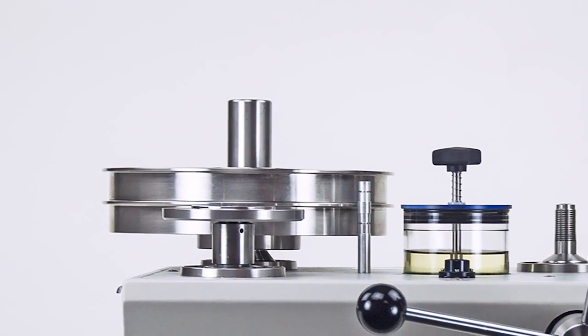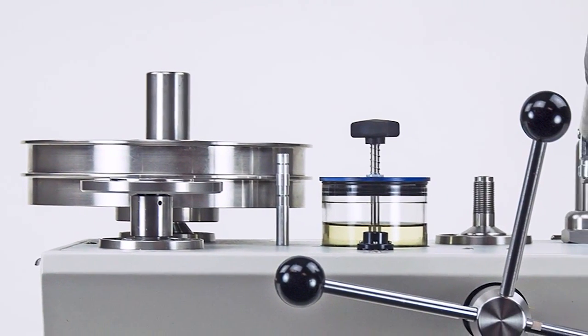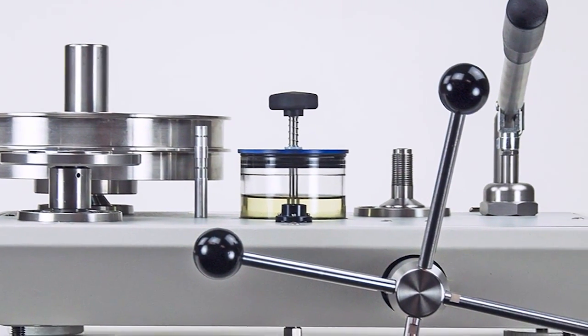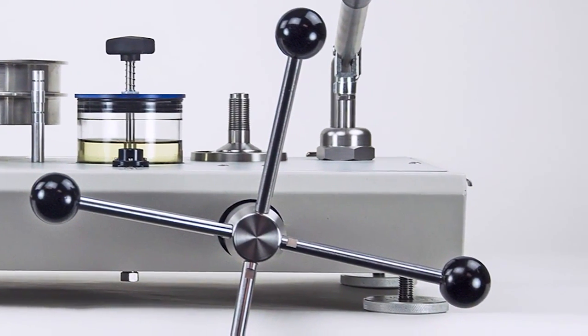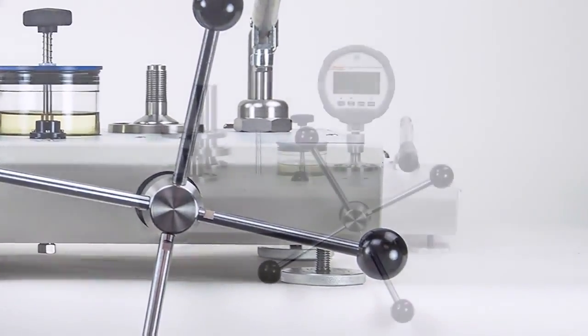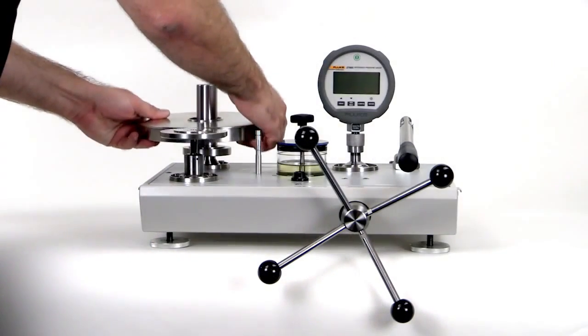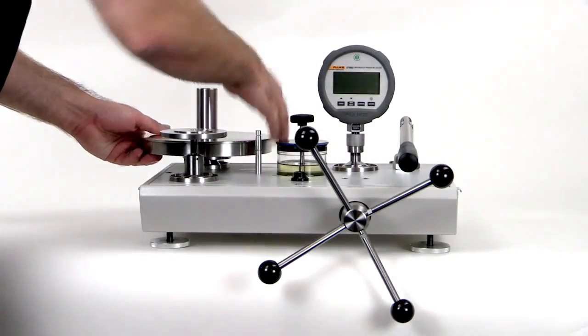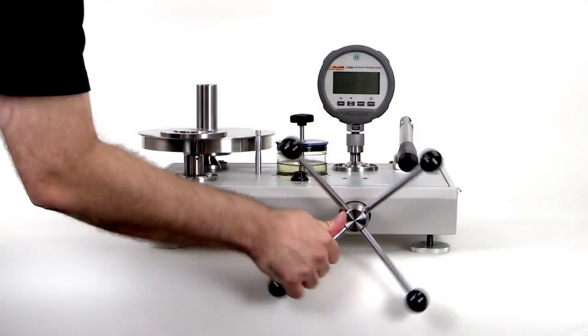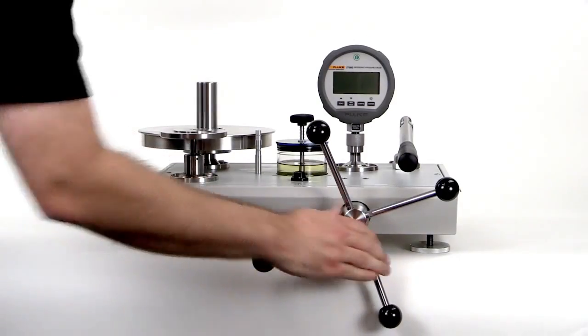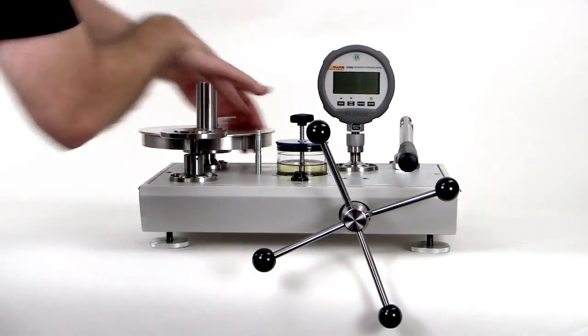A proper understanding of how a pressure balance determines pressure can ensure that it is used in such a way that is both sufficiently accurate as well as efficient. Depending upon the design, the physical operation of the unit can be relatively straightforward. You simply set the necessary mass on top of the piston and increase the pressure under the piston until it is floating.